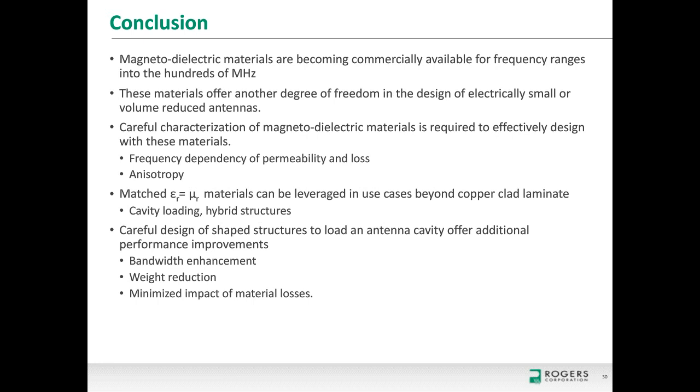Okay, no problem. Do you have frequency independent materials with a low tangent or loss tangent? For example, for 2 gigahertz with a permittivity and magnetic permeability equal to 2, or for 1.5 gigahertz equal to 1.5, etc. We're looking at that. The trade-off is generally correct, right? So if we're going up in operating frequency, we will be going down in permeability. The real tricky part comes in that the dielectric constant is coming from a mix of the ceramic properties and the polymer matrix properties. And the lowest dielectric constant polymer that's out there is something like 2.1. So your permittivity is always going to be something higher than 2.